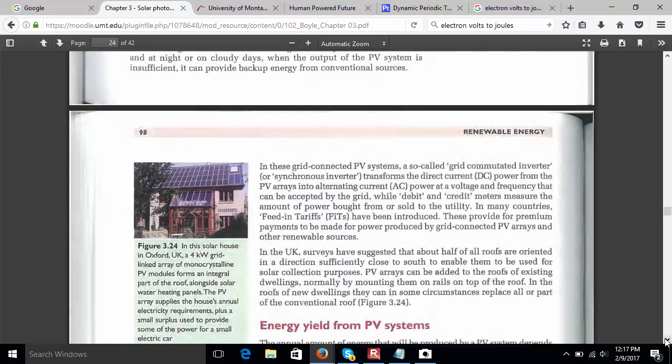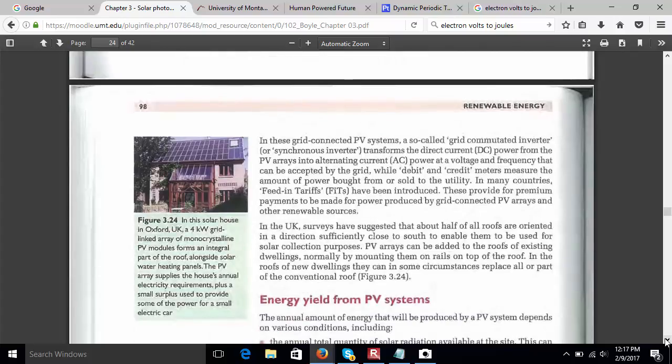There's a 4 kilowatt system. Most systems in Missoula you'll see are 2.5, maybe 3 kilowatt systems, and that is typically more than enough to zero out your bill and just pay your connection fee. What's it usually cost for polycrystals to set up? I'm seeing $4 a watt typically right now in Missoula, so 10 grand for a 2.5 kW system.